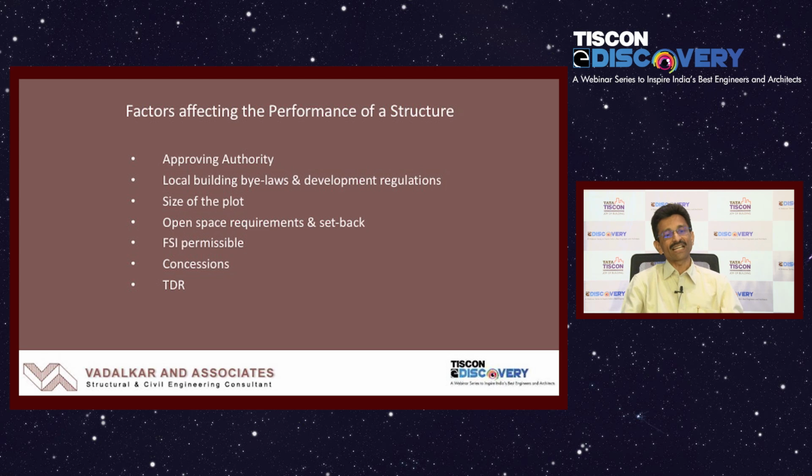So that's why the approving authority or local building bylaws are also very important in controlling the type of damages, because a lot of damage occurred because of the large projections and cantilevers, and a lot of floating columns were also used in those types of construction. My point is, if you have bylaws which allow something and people are exploiting the loopholes in the bylaws to build more and more constructed area without counting in FSI, then that is what is going to happen. I think that is a very important point we have to understand and remember.